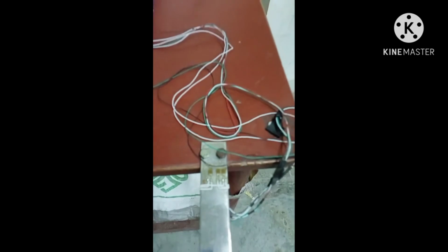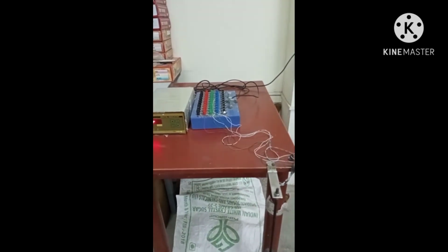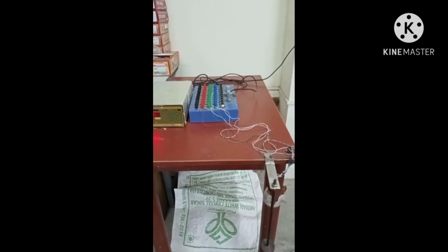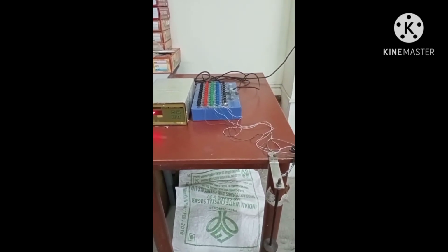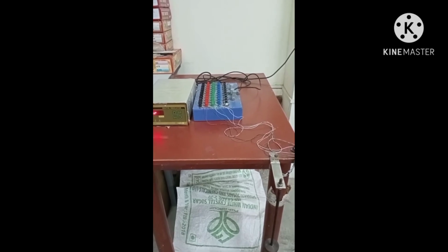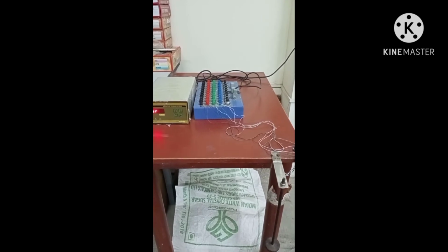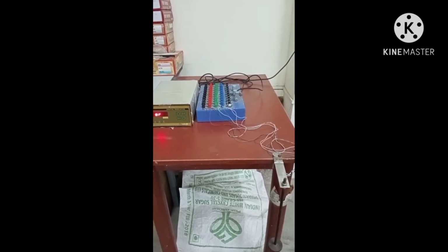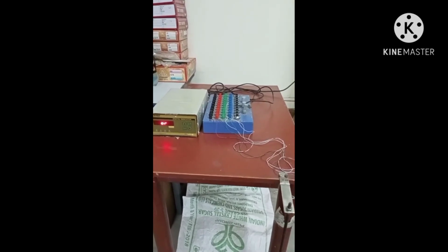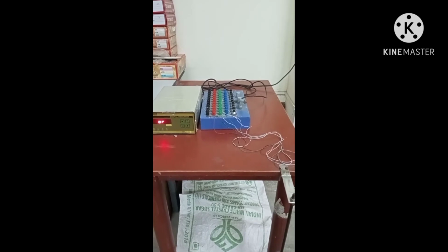So what is a strain gauge? Do you know what a strain gauge is? The strain gauge is used to measure the strain. How is it measuring the strain? It measures the strain when it is subjected to loads. When it is subjected to strain or elongation, the resistance will change. The resistance is measured electrically. By measuring the resistance, you will be able to measure the strain. So in this experiment, you can get the strain.